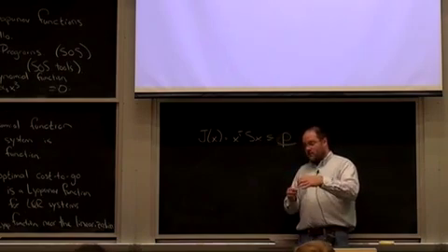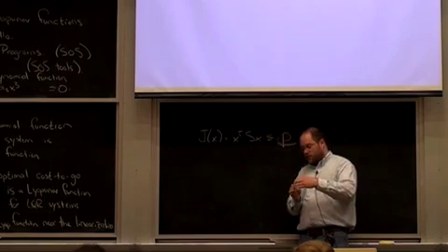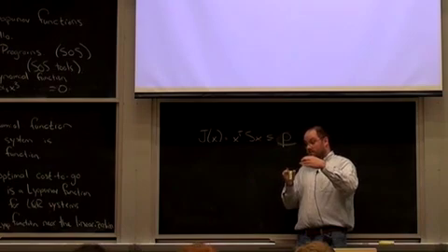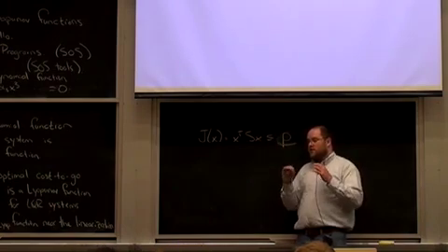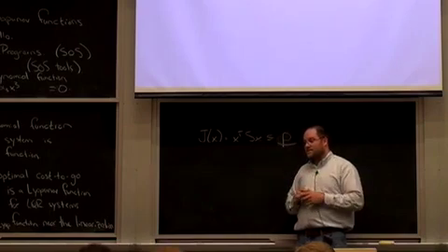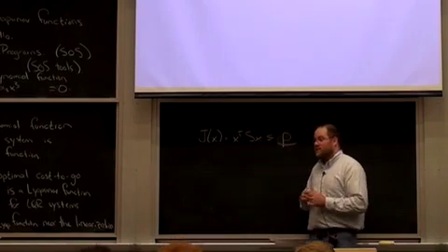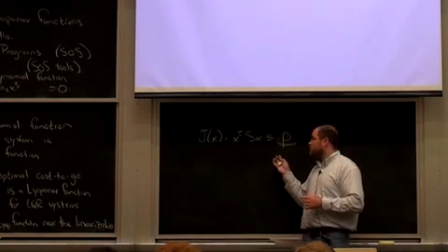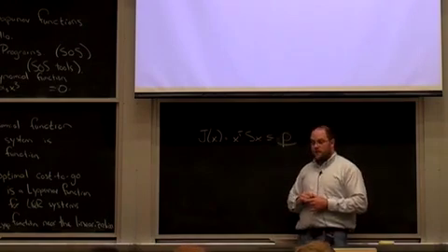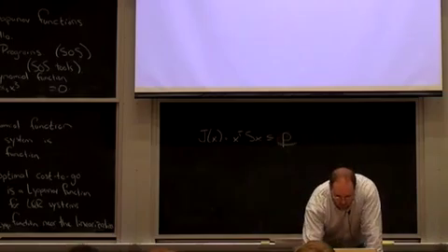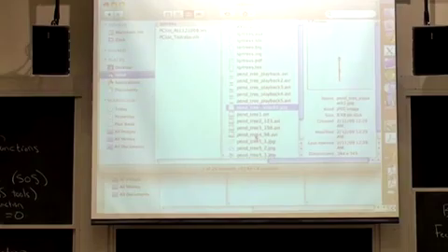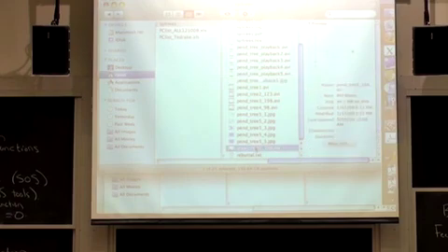You're asking if I could choose a different shape based on the contours. What we've elected to do, and I think it's a tighter version maybe than what you're saying, but it could be wrong, there could be better ways, is to find the biggest contour such that the next higher order terms of the linearization don't break the negative definiteness. So this is just for purposes of choosing a shape. This is choosing my shape. Okay, so I'm going to make this all concrete right now by trying to show you an example here.